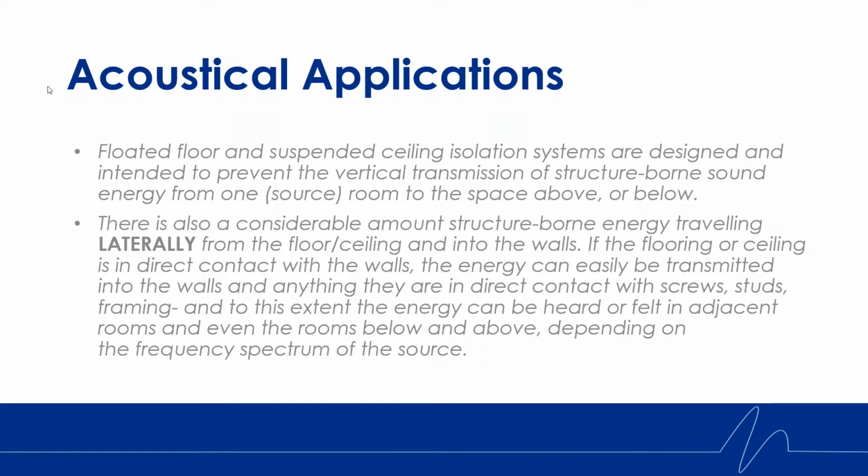Today, for the purposes of this presentation, we're going to be focusing on short-circuiting as it relates to construction materials or systems within a building. So let's start with acoustical applications. We have our floated floor and suspended ceiling isolation systems, or resiliently supported ceiling isolation systems, that are, of course, designed to prevent the vertical, the up and down transmission of structure-borne sound energy.